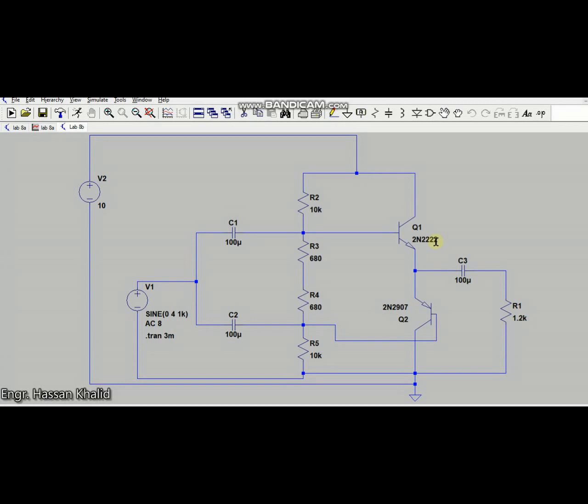So the combination can be formed by connecting the same type of transistor, one in the NPN mode and the other one in the PNP mode. That means that I'm using the symmetry of one transistor form. So this type of configuration is also called the push-pull operation that will help us to receive the signal from the positive cycle of the input signal as well as the negative cycle of the input signal toward the output side.